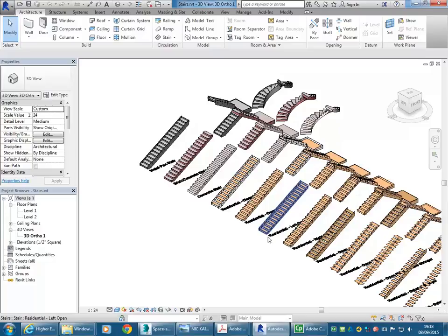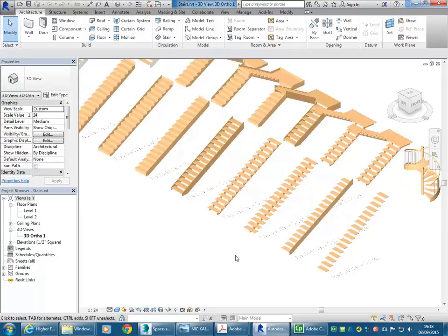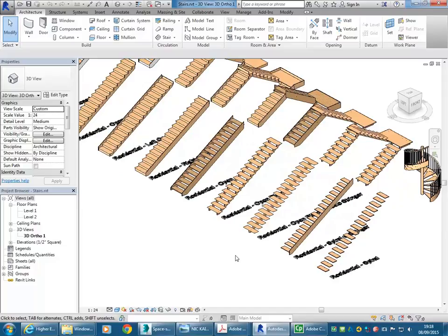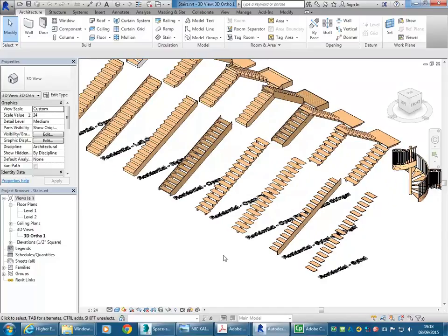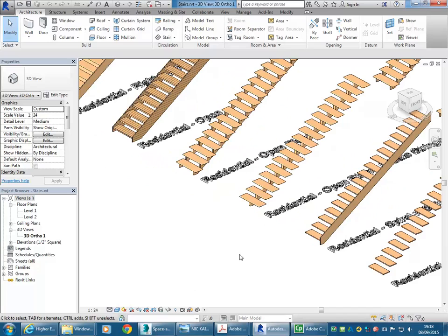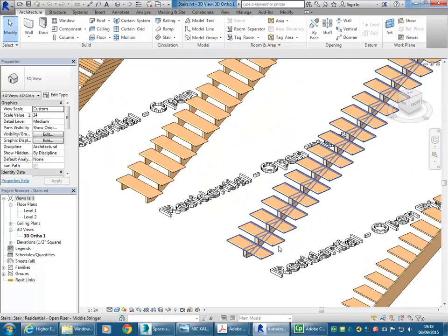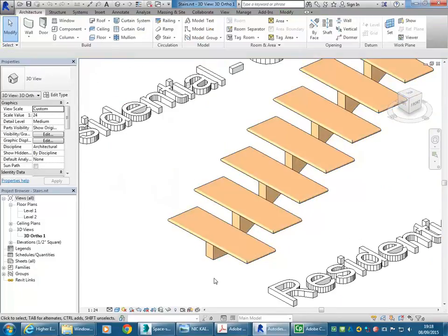So notice we've got all these pre-made stairs. After a while you'll realise you can make all of these just by fiddling with the properties in any stair you make yourself. But it still saves time if you can get them from this library, essentially. So say I want to keep it fairly simple because I do want to put a glass balustrade on the side, and with a stair like the one I'm tempted to choose with the middle stringer, that's going to be a problem.